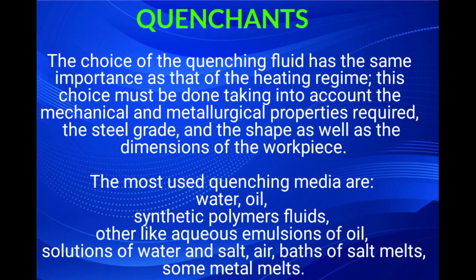Next comes the selection of quenchants. The choice of quenching fluids has the same importance as that of the heating regime. This choice must be made taking into account the mechanical and metallurgical properties required, the steel grade and the shape as well as the dimensions of the workpiece.